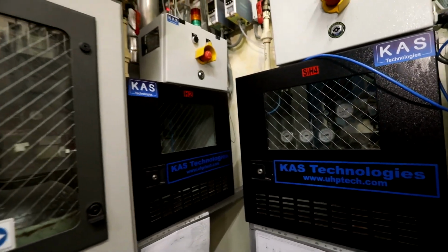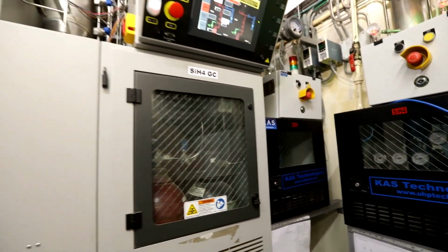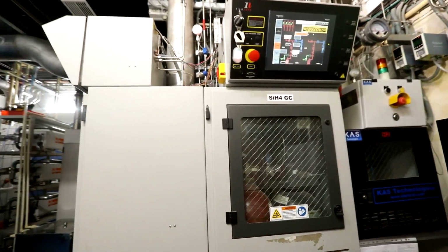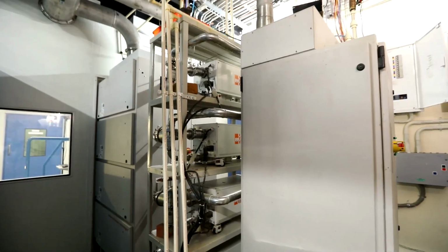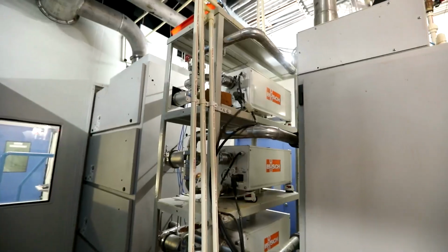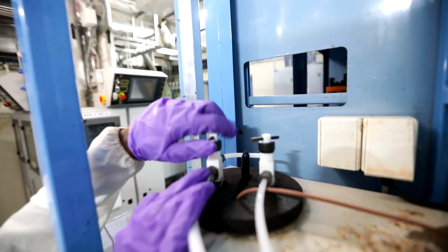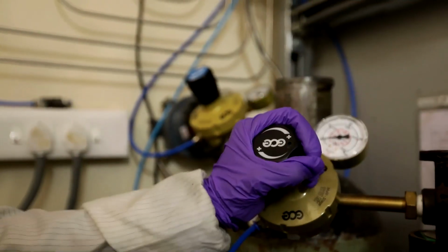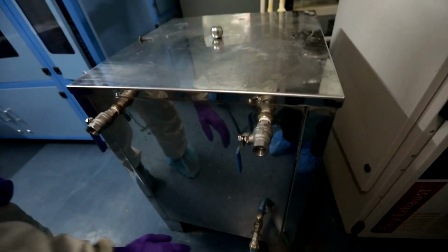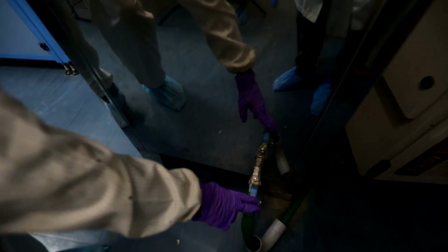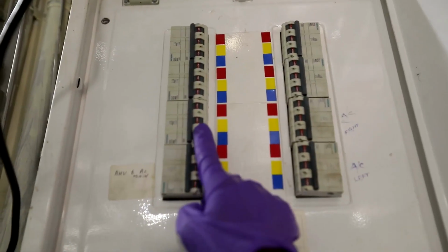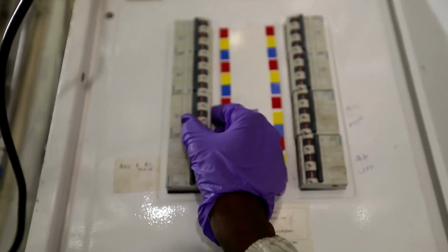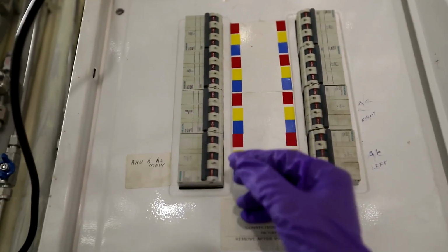Process start. Before starting the deposition, we need to check the gas lines, chillers, pumps, etc. For this oxidation, several gases will be used, such as nitrogen for purging, silane and oxygen for oxide growth. Once we make sure that the gases and the pumps are all operational, we switch on the LPCVD system, that is, controller and power supply.